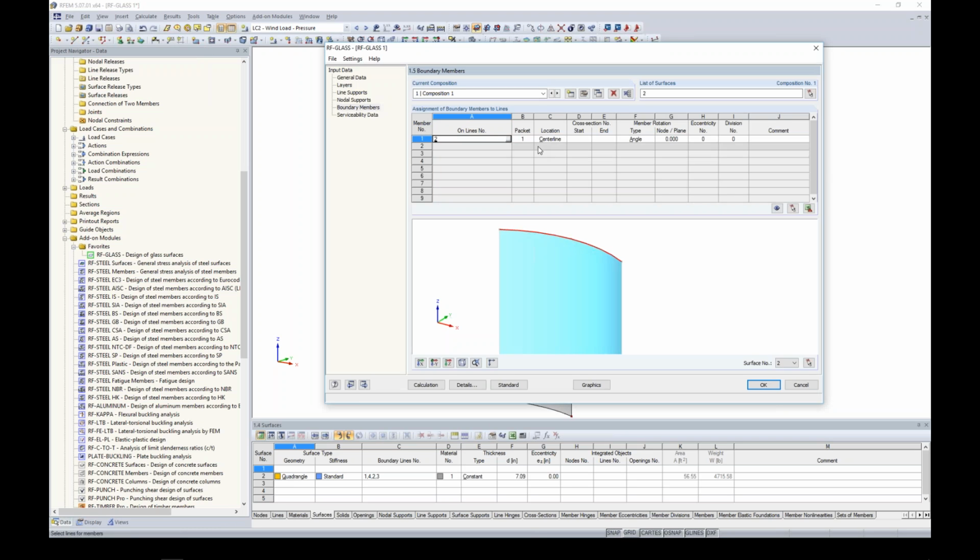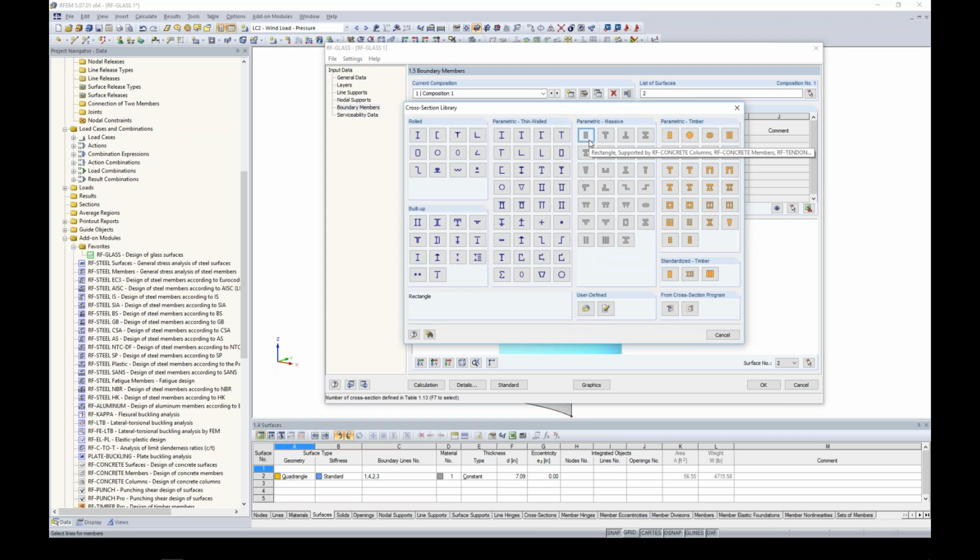that member to run. And you'll notice that everything is just set to center line because I'm using 2D plate analysis. I don't have any cross sections defined in RFEM. And normally you would think, okay, I probably need to go back into RFEM, create some cross sections, but the nice thing is I can do everything from this add-on module. So up pops my cross section library.